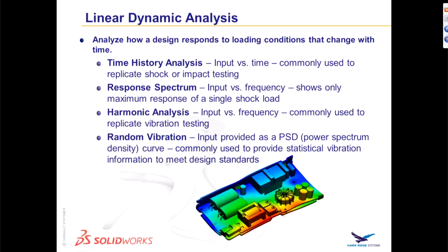Random vibration also is similar to that, where you're going to analyze the product over a frequency range, but random vibration is used when the exact nature of those individual vibration events may not specifically be known. For example, if you're trying to design an electronics package that is mounted to a vehicle that could be vibrating at unknown magnitudes or rates, or perhaps designing something to seismic safety limits where you are expecting earthquakes or other seismic activity to happen, but you don't necessarily know how big they will be or how frequently they are going to be occurring.